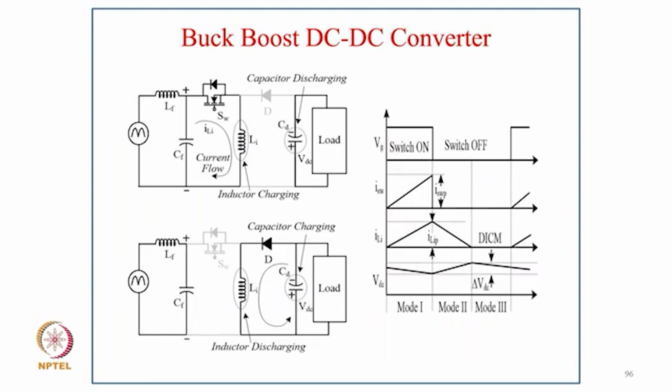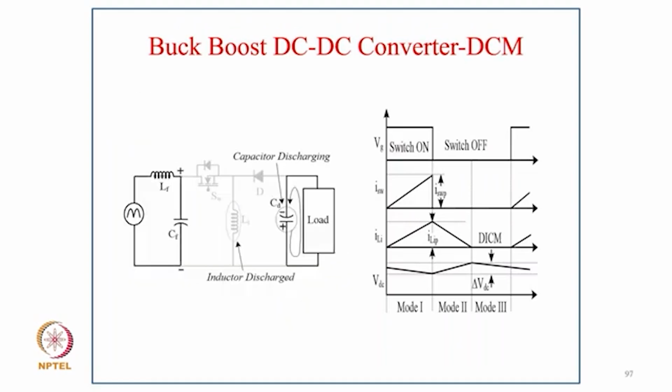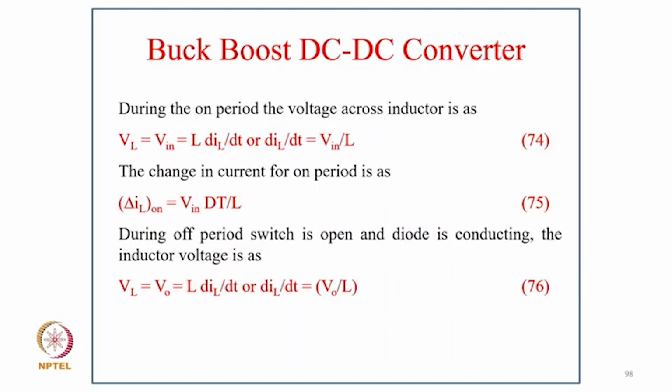also. So you have the device conducting, then the inductor conducting, so the diode conducts, and typically you have the output voltage and inductor current. So that is the third mode, where the diode and the device are both discontinuous, and you will have a DCM mode. Typically none of the two has current in this third mode in DCM.